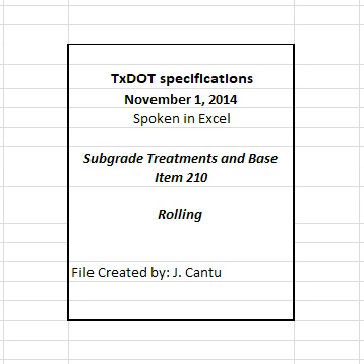2.2 Tamping rollers. Furnish self-propelled rollers with at least one self-cleaning metal tamping drum capable of operating in a forward or backward motion with a minimum effective rolling width of 5 feet. Mount drums in a frame so that each drum moves independently of the other for rollers with more than one drum. Operate rollers in static or vibratory mode. 2.2.1 Tamping roller, minimum requirement. Provide tamping feet that exert a static load of 125 to 550 psi and project at least 3 inches from the surface of the drum for all tamping rollers except for heavy tamping rollers.